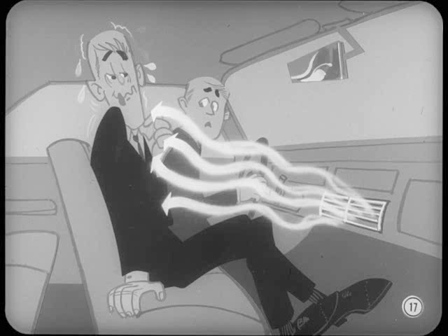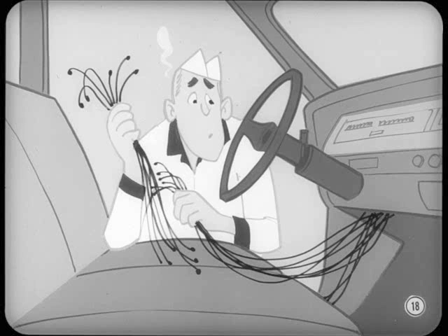For example, if you're supposed to be getting air from one place and it comes from somewhere else, you know that the logical starting place to track down the problem is at the air distribution doors. It might be a matter of pinched or improperly connected vacuum actuator hoses, or it could be that some linkage is not adjusted properly. These are conditions that you should recognize from your understanding of the conventional air conditioning system.